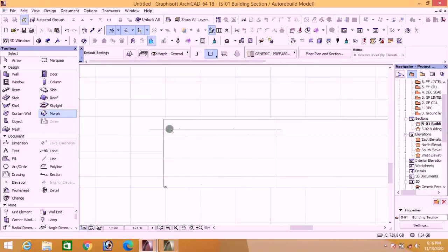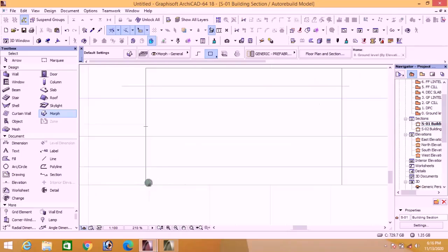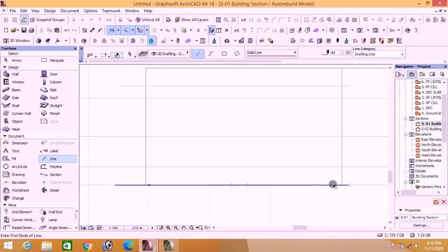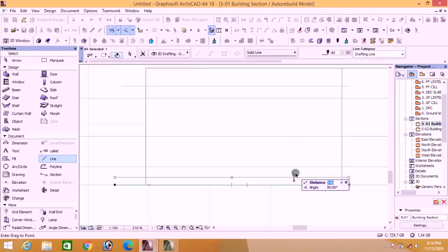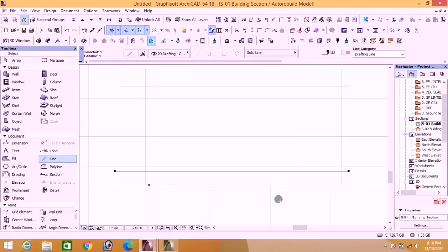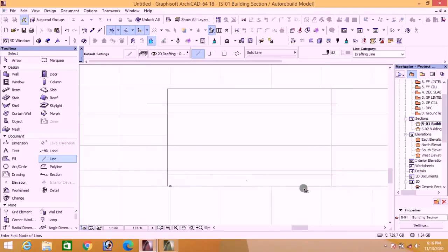And we want to draw a beam that will cut down this way in a stylish way. First, let us put the thickness of the slab that will be at this position. Use your line and measure it 450. Can you see that? Then get the middle. Copy here. Use a line and get the middle. Alright, let's change the color of this line to simply black. Now, follow me as I do the simple sketch of the beam that I want to be here.